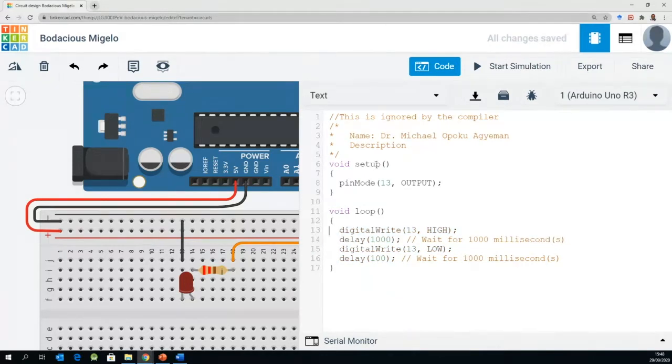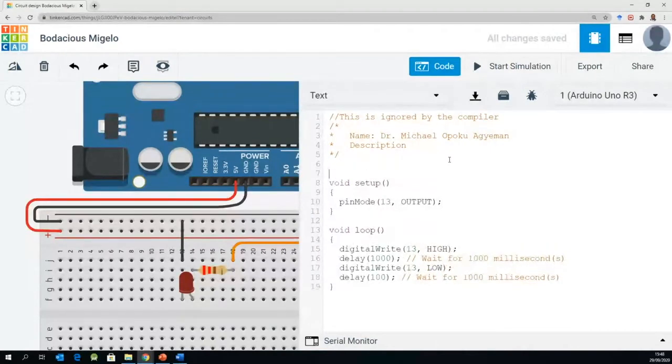So we can start off by using variables. At the top there, as you would with a preprocessor directive, we can define an integer. So we define int, let's call it LED pin, and we say that is equal to 13. And each line ends with a semicolon.